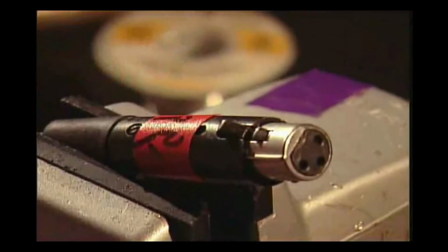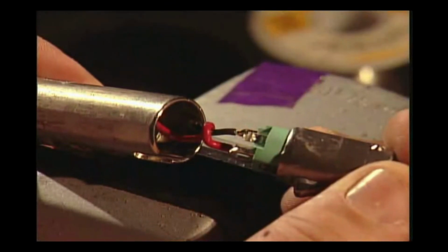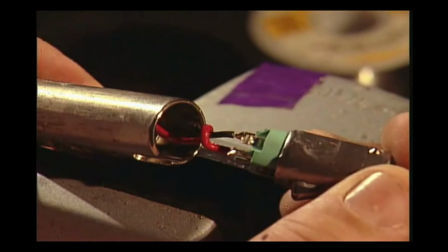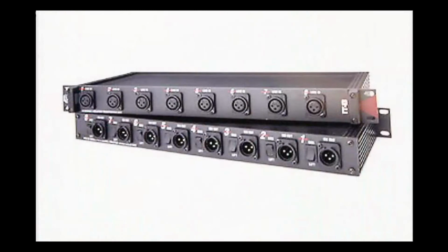Another method is to purchase modified shunt adapters, which have the ground wire already lifted from pin 1. You can then simply connect the adapter to the female XLR connector on the cable you need lifted. There are several systems on the market which provide isolation transformers with ground lift switches. Here's the Proco IT8A, which provides 8 channels of isolation transformers with ground lift switches. A device of this type would eliminate the need for lifting the shield ground on the cable itself.